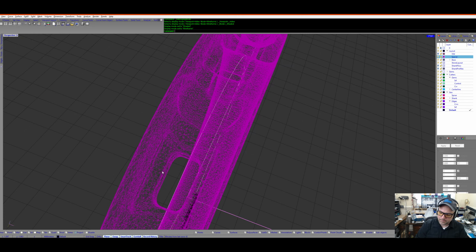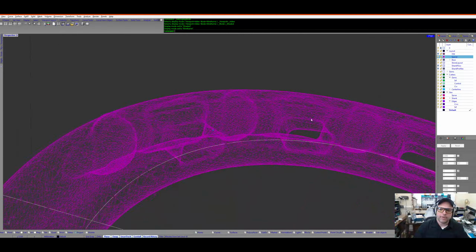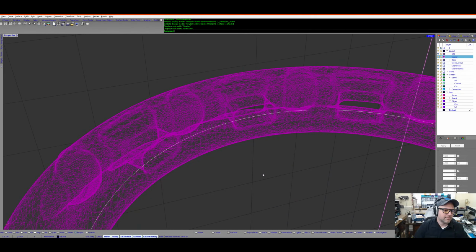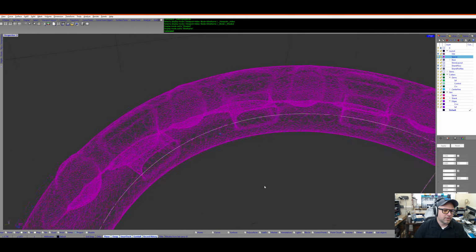I don't want to do fillets, or sometimes I do a fillet in Rhino. If I look at it and go, Rhino can handle that, no problem, I'll do a fillet in NURBS, and then there's no reason to go to sub D. But if I know Rhino's going to have a problem doing that fillet, then why would I want to go and do sub D, where now I have to do every little link and adjust the edge to it?